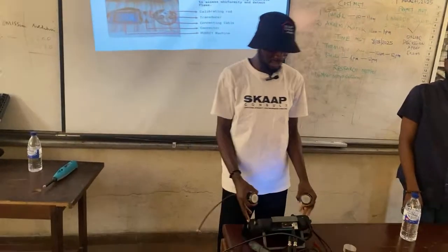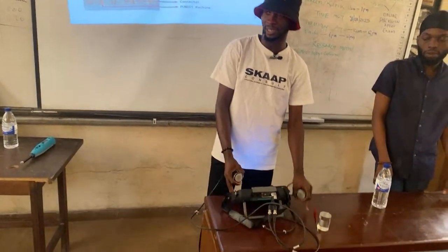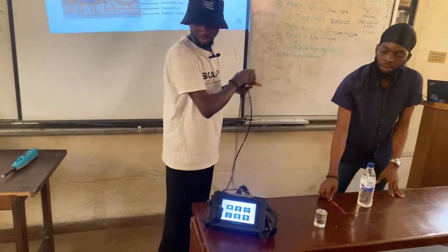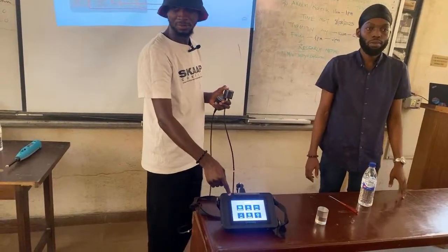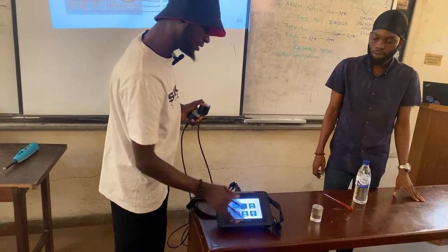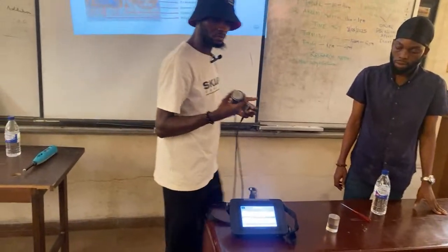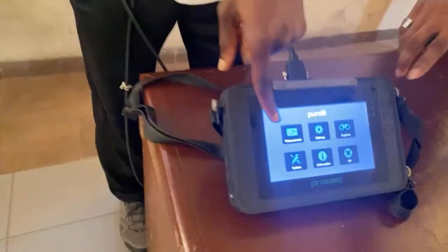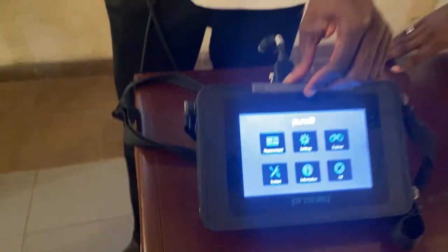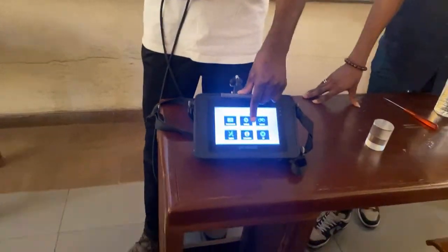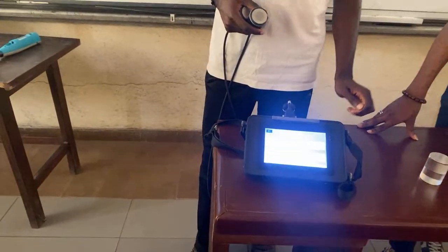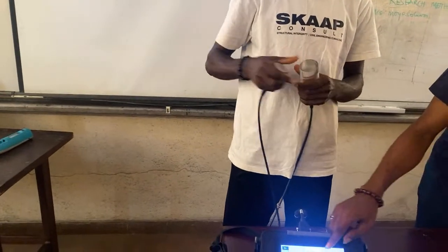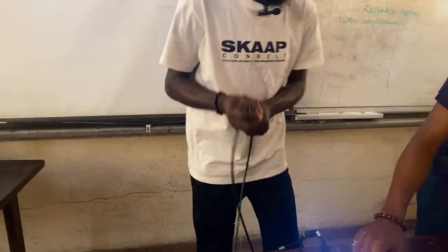So like I said, the machine has been in a state of rest before, so you have to calibrate first so that it can work optimally. So this is the interface of the machine now. So then you come to settings, calibrate. So this is the measurement space. So you come to settings. Then you take your calibrating rod. And then you hit on.